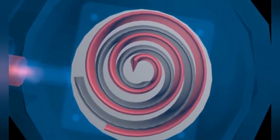The type of compressor used is the scroll hermetic type. The scroll compressor works as follows: gas at low pressure and temperature enters the suction line and goes into the compressor. The low pressure and temperature gas is pressurized by the scroll compressor to high pressure and temperature gas. The high pressure and temperature gas then passes through the discharge line and goes into the condenser.